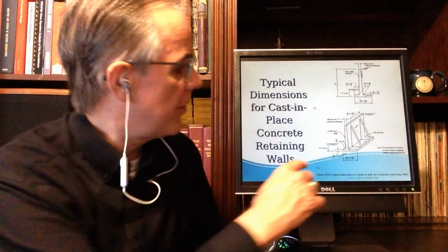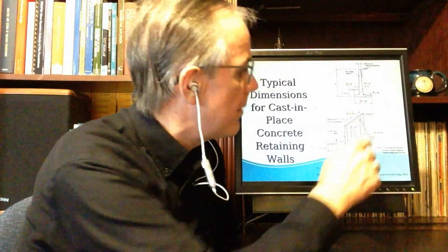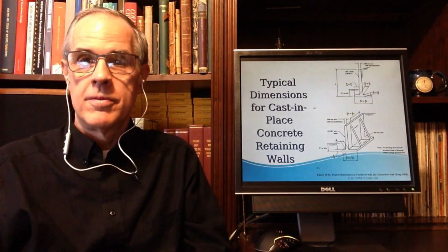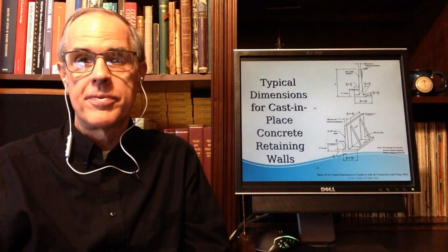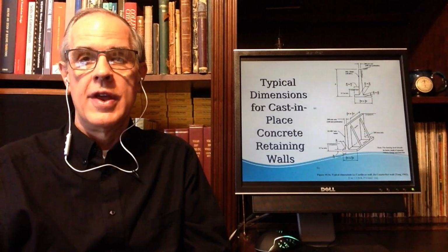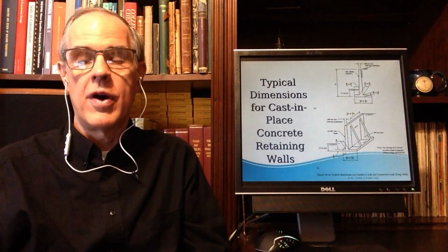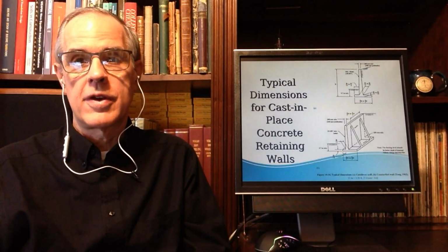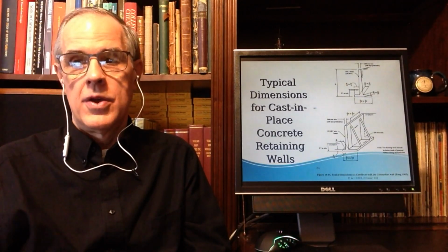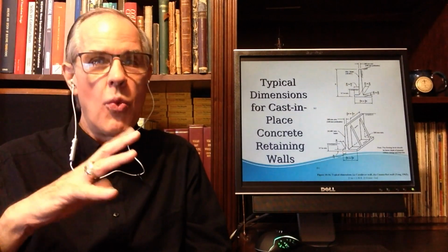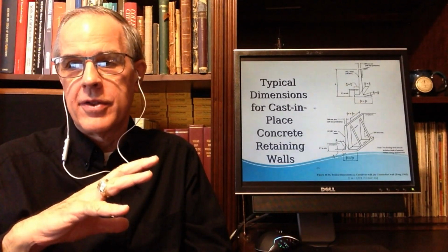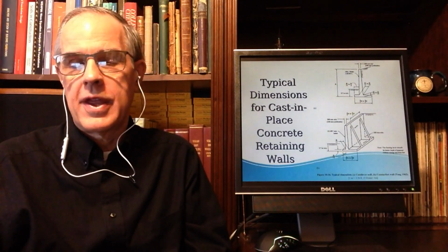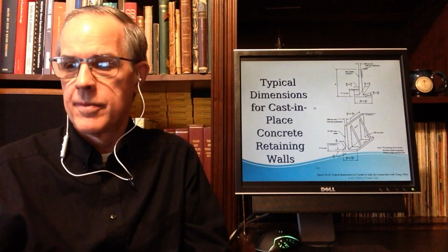It also shows you this counterfort wall in a little bit easier format using this nice isometric drawing, the ribs, which give greater structural integrity to the counterfort wall. The geotech analysis of a counterfort versus a cantilever wall is identical. It may be a little bit more weight because it's concrete rather than soil, and we can probably neglect that. The counterfort is strictly for structural purposes.